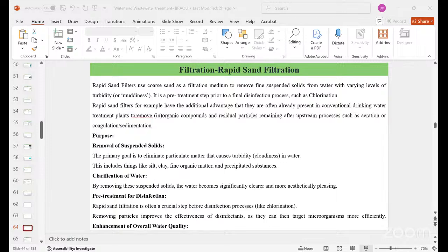The filter medium is a key component, and it is made up of porous materials such as paper, cloth, or sand; membranes with microscopic pores less than 0.2 micrometers; and granular substances such as gravel and activated carbon, which are the main granular materials used for filtration. The major driving force for filtration to occur is to push the fluid through the filter medium. All right.